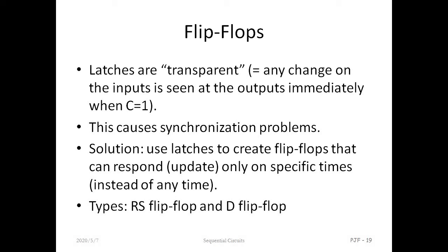Again I will repeat the definition of latch. Latch checks all the inputs and correspondingly it changes the output. These are called latch, for example the SR latch. This causes a synchronization problem, and to remove the synchronization problem we use latches to create a flip flop that can respond and update only at a specific time instead of any time. Types: RS flip flop and D flip flop.